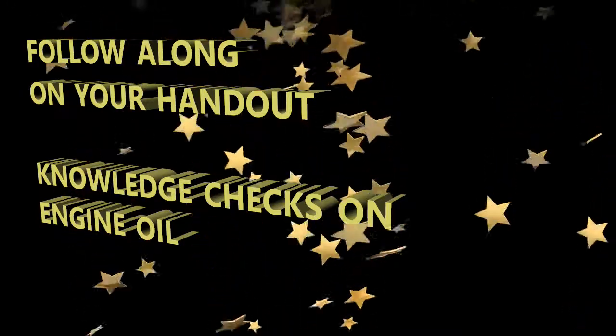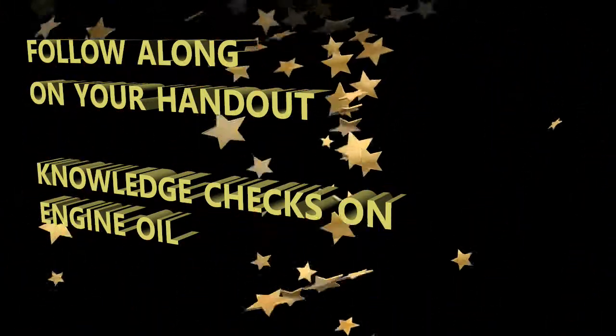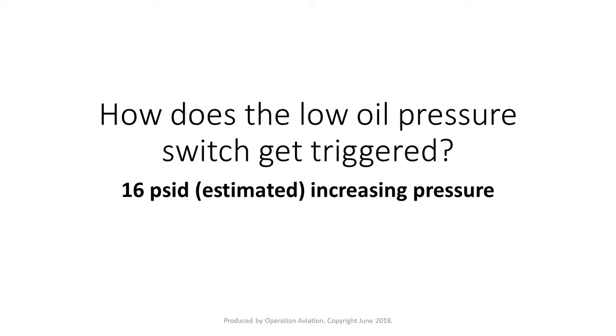How does the low oil pressure switch get triggered? Is it through 11 psi increasing pressure or 16 psi increasing pressure? I didn't mention the 16, but I'm mentioning it now. That low oil pressure switch gets triggered at 16. Just remember that, because oil pressure has to be at a certain level.